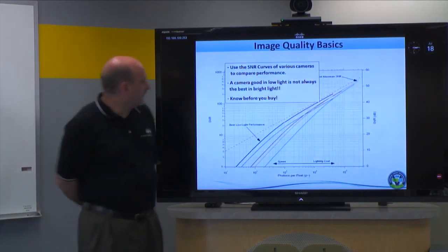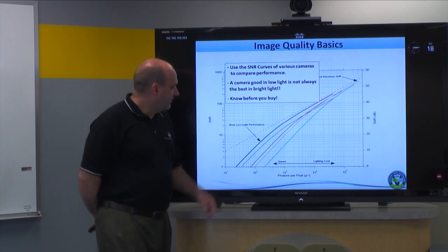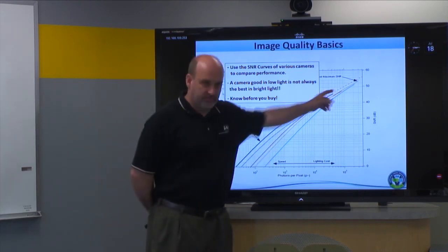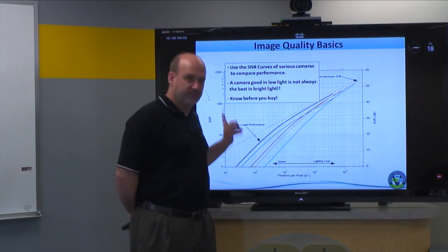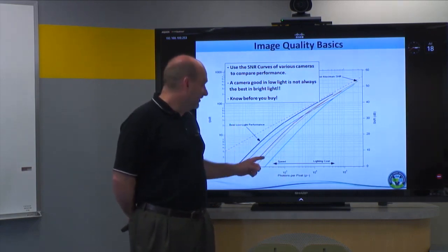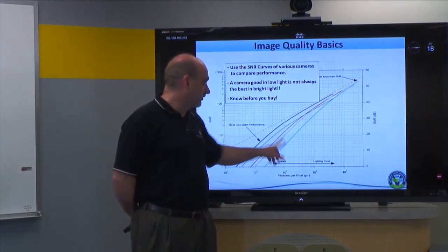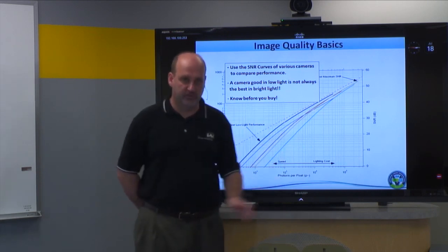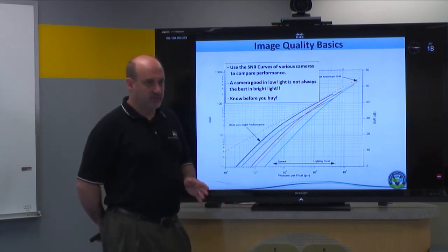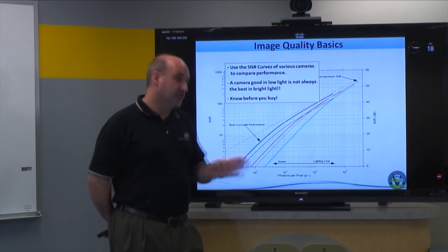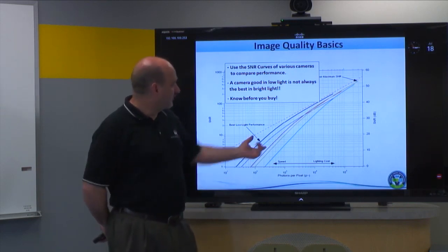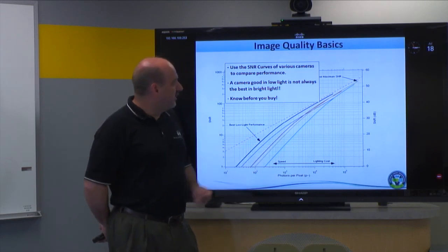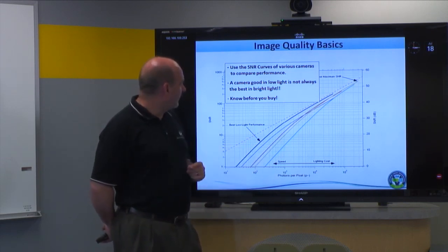If available from the manufacturer, you can get signal-to-noise ratio measurements. Typically, this is only good from a manufacturer. You're dependent on the test conditions, so it's not usually good to compare one manufacturer's curve to another's and say, oh, all things were equal here. But if you can get them, either in absolute terms where you could compare one camera to another, or for several cameras from a manufacturer, you can tell things about the camera then.